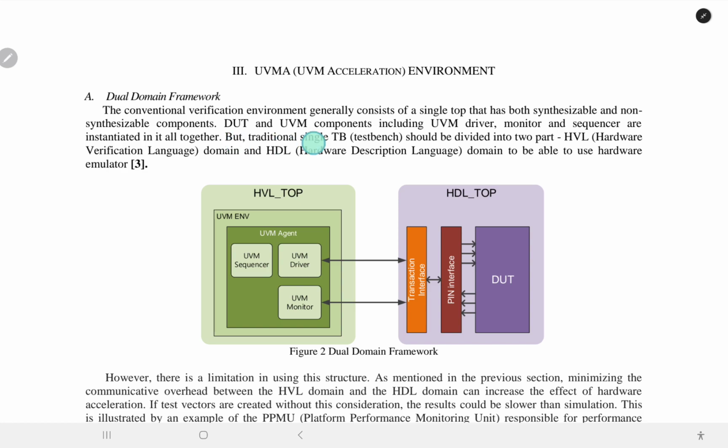But the traditional single TB test bench should be divided into two parts: HVL, Hardware Verification Language domain, and HDL, Hardware Description Language domain, to be able to use a hardware emulator.